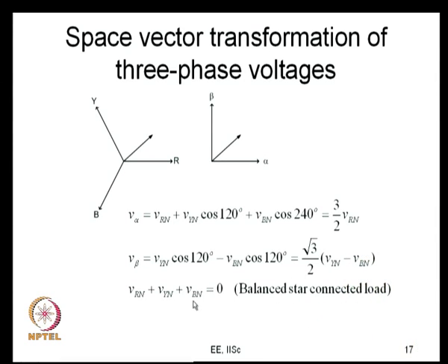So, n is the load point neutral. Okay. So, now Vrn plus Vyn plus Vbn is equal to 0. Under this condition, what you can say is you go by your same thing as V alpha is equal to Vrn plus Vyn cos 120 plus Vbn cos 240, and that adds up to root 3 by 2 Vn. The same mistake is perpetuated here also.